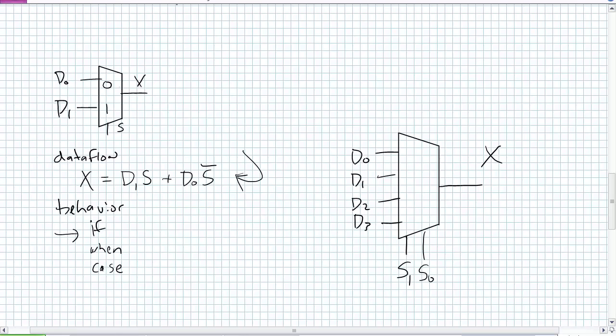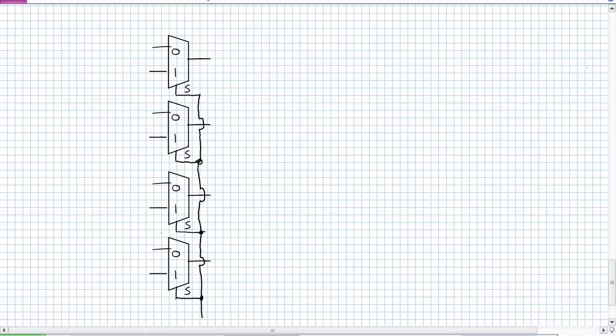So let's continue with some discussion of multiplexers potentially hooked up in a different fashion, making use of a single serial line. Consider, if you will, this arrangement of 2-to-1 multiplexers. This is what's known as a quad 2-to-1 multiplexer. What's quad? It's four 2-to-1 multiplexers. These things are especially handy when we go into display multiplexing. One of the definitions of display multiplexing is using a single driver to display 2 different numbers or 4 different numbers or 16 different numbers on 16 different displays.